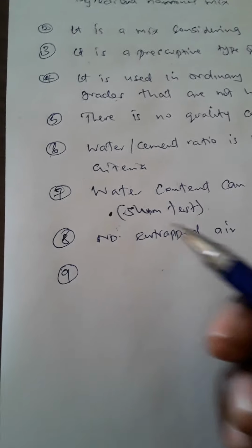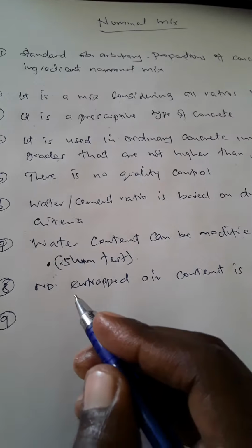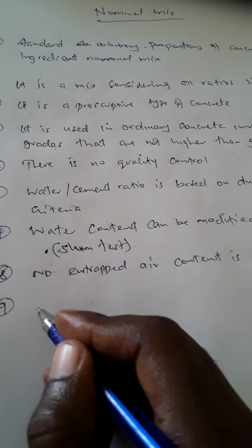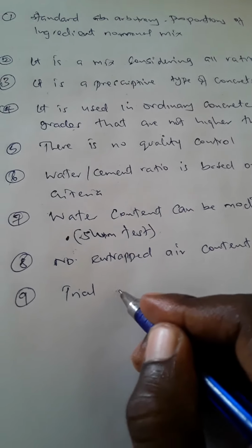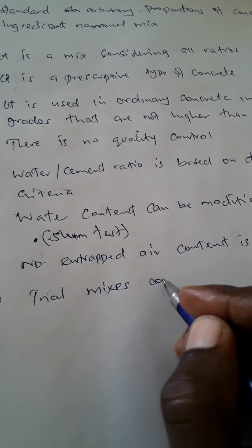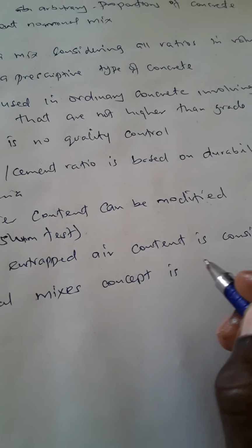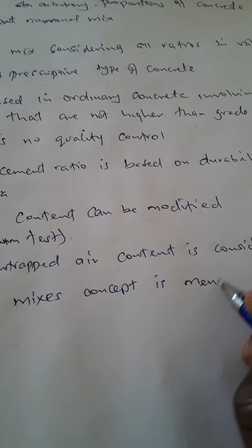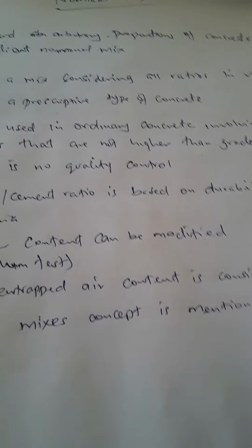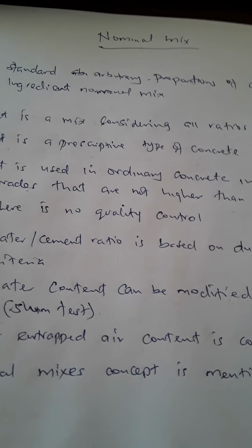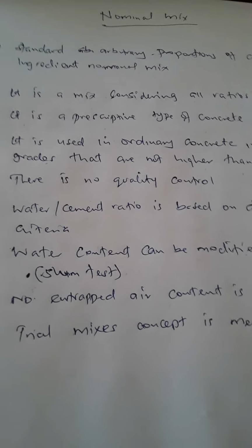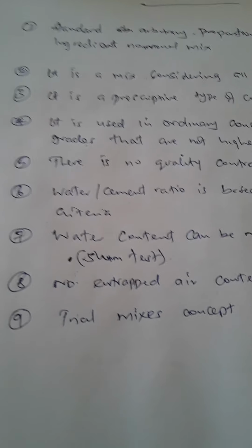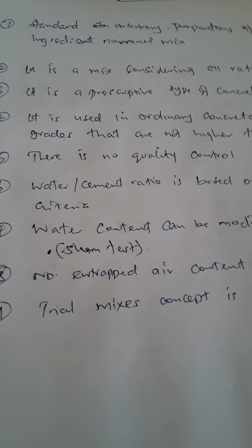And then the last point that we are going to note about the difference between the nominal mix and the design mix is that in nominal mix, the trial mixes concept is mentioned. So those are the differences between nominal mix and the design mix. If somebody asks you a question or to differentiate between nominal mix of concrete and the design mix of concrete, these are the points that you are supposed to know.